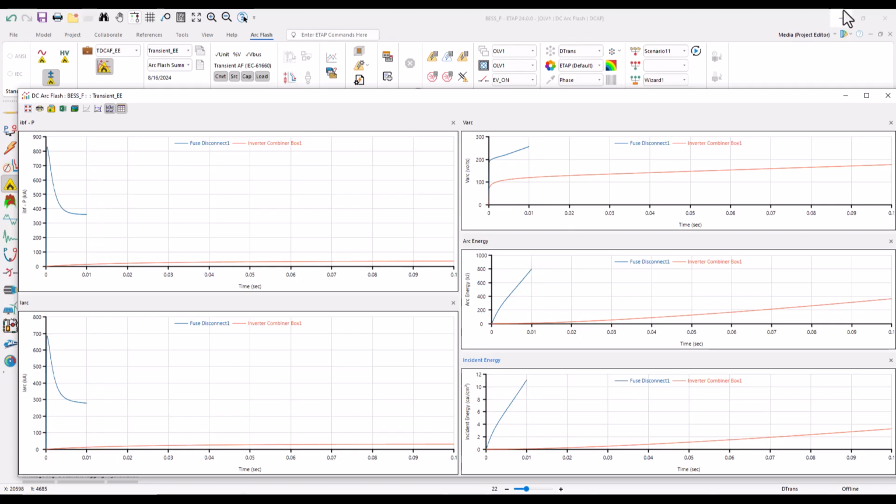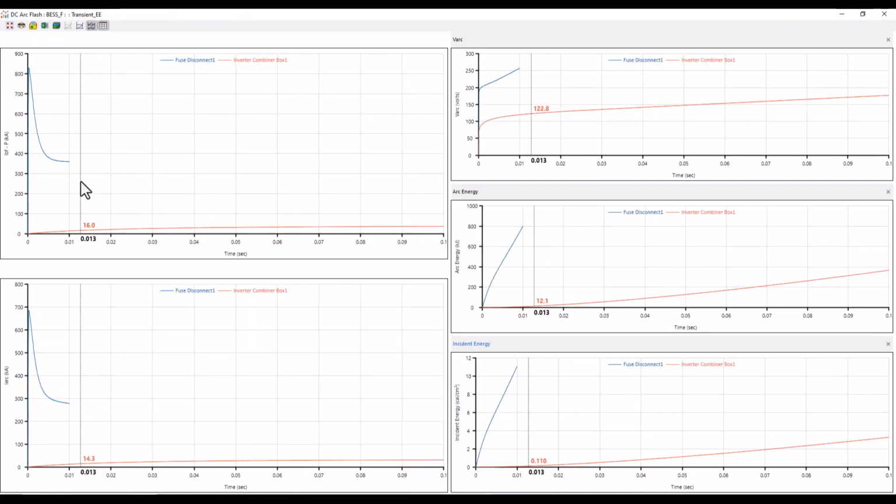So this overall graphical representation clearly helps us out on how the dynamics of the arc put together with the dynamics of the short circuit of the battery systems, the DC capacitors, the DC loads, could be an ultimate solution for arc flash in accurately estimating the incident energy rather than printing arc flash labels that are overly conservative.